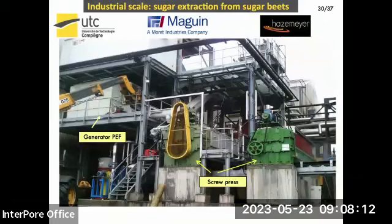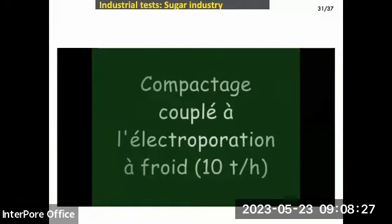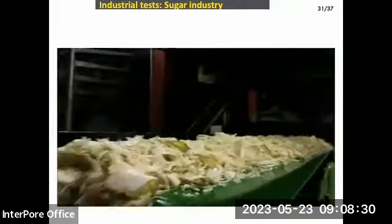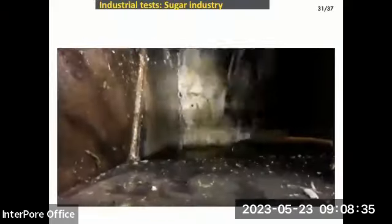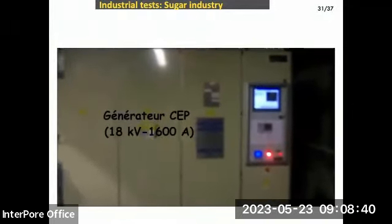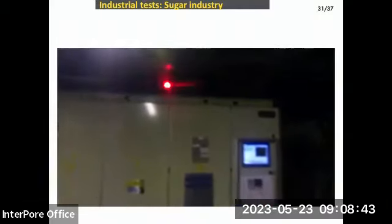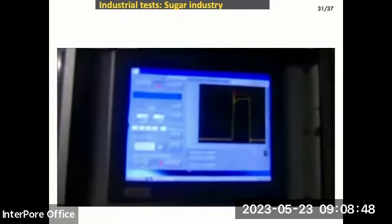Here you can see a photo of the industrial installation with the pulsed electric field generator and with presses for such a process. I will show a short video. So you can see here the treatment was 10 tons per hour. Here are the cassettes obtained after slicing the beets. And the cassettes go continuously to the treatment chamber. Here is the generator of the pulsed electric field treatment. And you can see the form of the pulses, which is a square form.